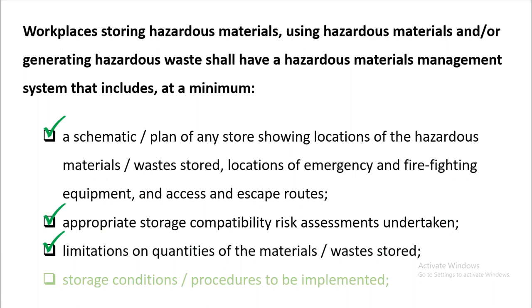Otherwise, you need to separate them by a certain distance, because if they are not compatible with each other, they will react to each other, and maybe it will explode, or it will generate harmful gases in your area, or it will generate a fire. So always check the appropriate storage compatibility risk assessment.